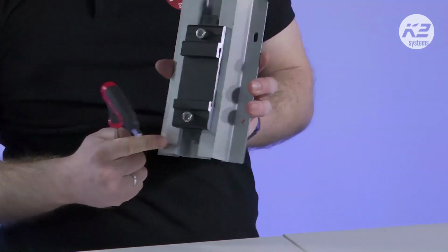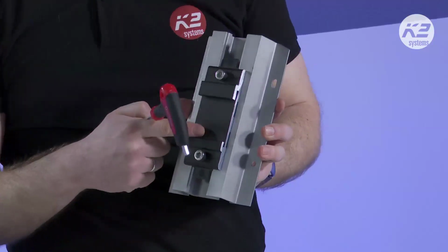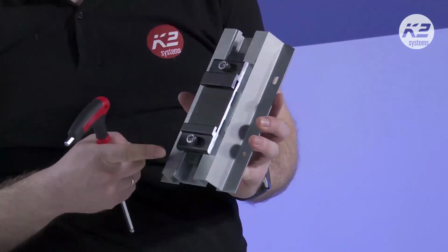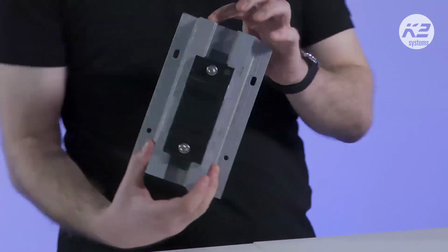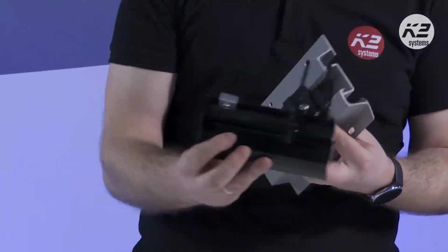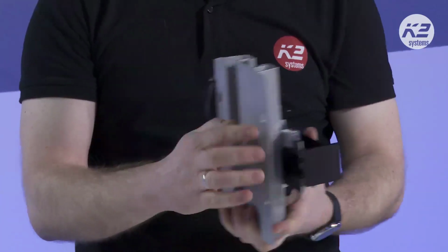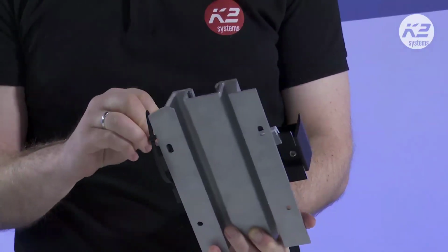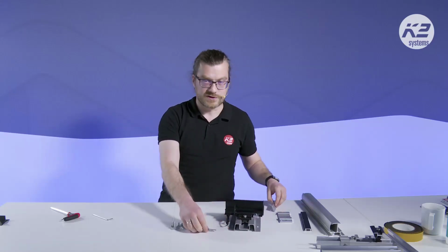This CarrierRail we have only in silver color. So you will need to install these black components, and you will see only the ends of the rail, so it's almost not seen from the ground. Install the cross connector here. Install our insertion rail here. Just put it inside and fasten it by a spring plug from the side. I will show you on our kit, on our model exactly.